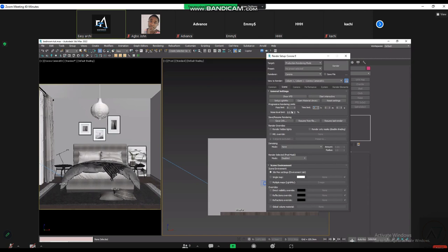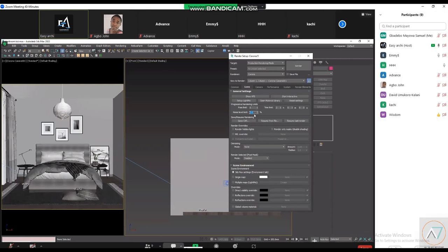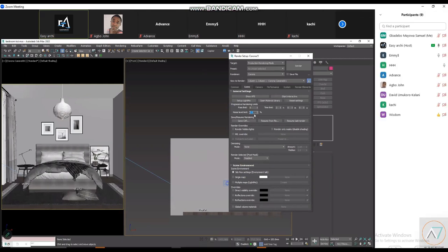And we have this other option, noise level limit. This is the guy I use. This is my guy. I use noise level limit for interior scenes. I use a noise level limit of 3 to 5, depending. Between 3 and 5, I think you are good because the denoiser is actually big.